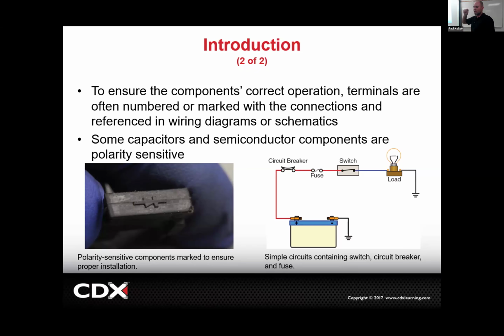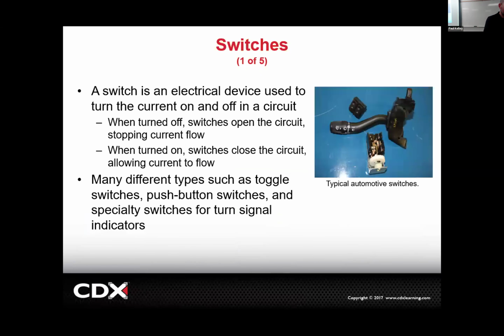But if you change your regular incandescent style bulb to LEDs, actually you can probably put it in backwards and it just won't work. Because remember, the diode is a one-way check valve, like a gate. So sometimes you've got to look on the part, like this diode, for example, and make sure you put it in the right direction. Cool, just a little bonus.